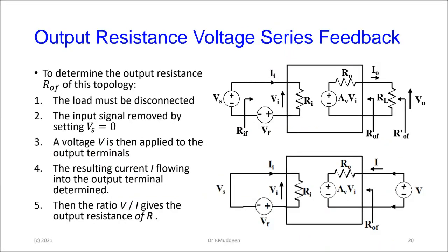Okay. So how you do it, I have two diagrams up here to show you as we move from one to the other. What you do here is a little bit like the Thevenin analysis that you would have done for circuits before. We're going to short out some things and remove a couple of things. The first thing is that the output resistance of the amplifier is independent of the load. So get rid of the load. We're going to take the load out.